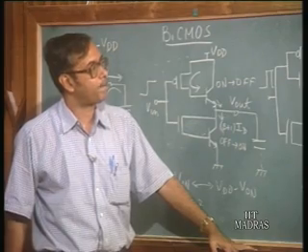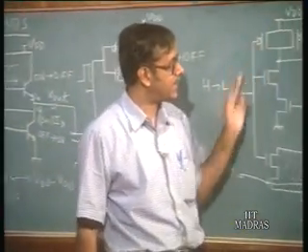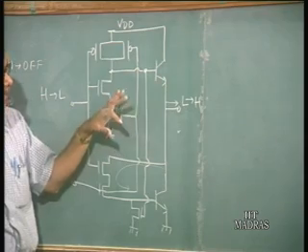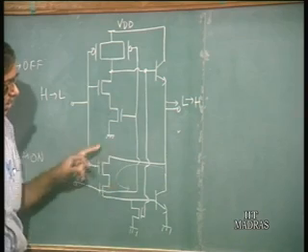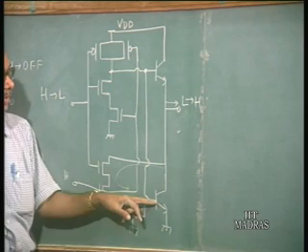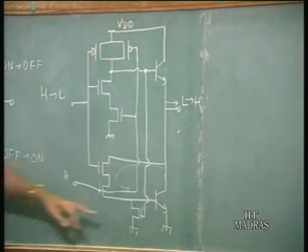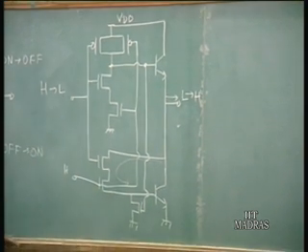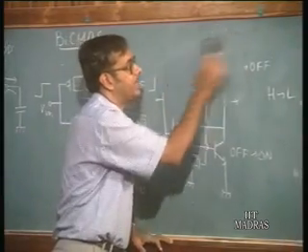Okay. So, what we basically have is a CMOS NAND gate here. This is a BiCMOS NAND gate. We have the N block of the CMOS here, which is actually driving the lower bipolar transistor, and then the output of the CMOS NAND gate is driving the gate of this NMOS transistor here, okay, which is helping to switch off the bipolar transistor. So, now if you look at any BiCMOS circuit, we can actually derive it from the CMOS logic circuit by drawing it in this form.